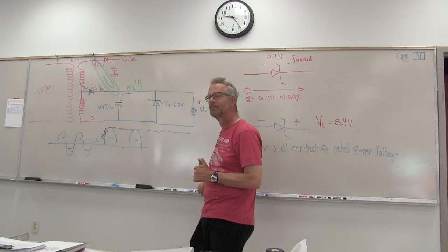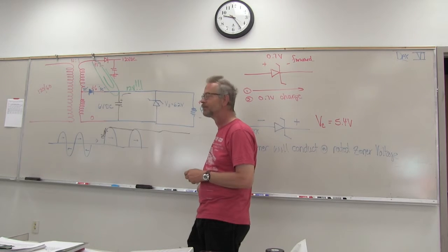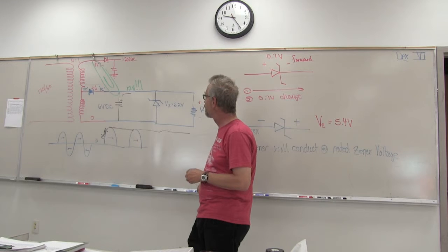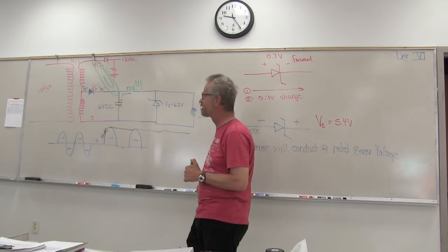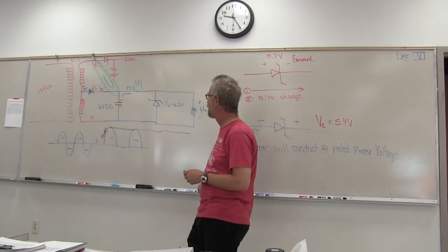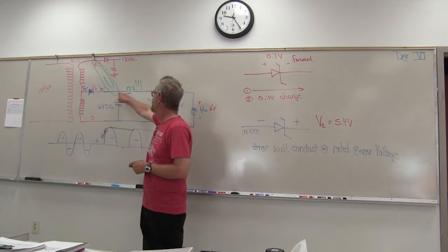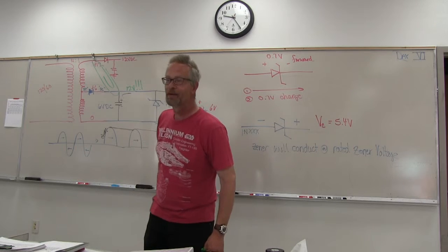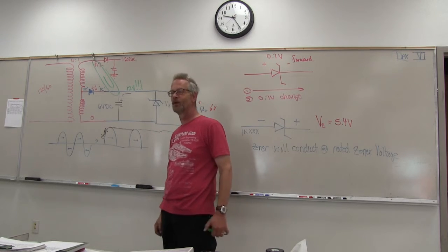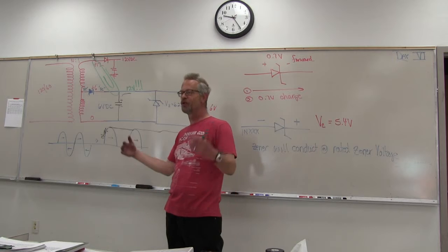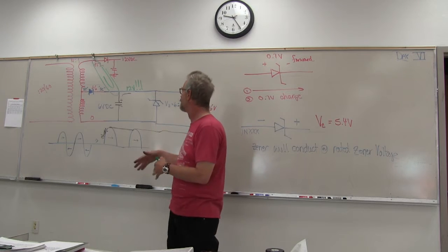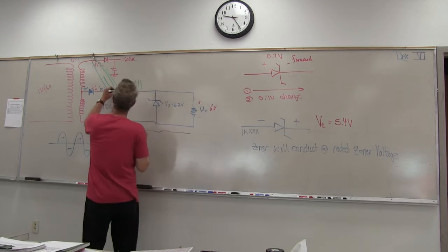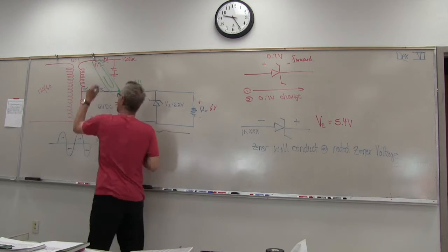Yeah, so what you're saying is that diode burns out and it's just nothing but a wire. No, what I'm saying is we have 12 volts elsewhere in the circuit, and somehow, by mistake, that 12 volts got shorted out to this 6 volt line. Because somebody dropped a paper clip in the circuit somewhere, or something happened and shorted out 2 things in the circuit, so that what's supposed to be getting 6 volts is now connected up to 12 volts.